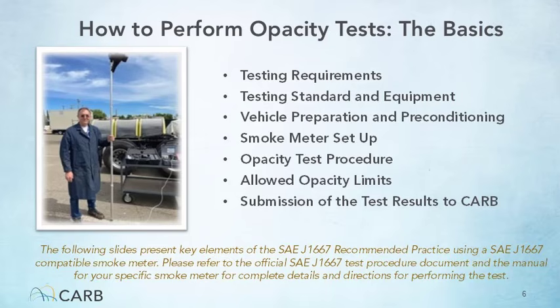One important note is that the following slides present elements of the SAE J1667 recommended practice using a compatible smoke meter. However, these slides are not all-inclusive and are not a replacement for the test procedure document itself. You should read the official SAE J1667 test procedure document prior to performing the smoke opacity test and refer to it as needed. Additionally, refer to the owner's manual for your specific smoke meter for complete details and directions for setup and performing the test.